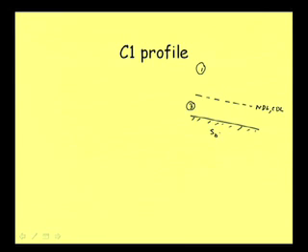So, here SB is equal to SC, and of course, it is positive. Well, so this profile C1 will be a rising profile like that, because we could see that if the flow depth y is more than yn, then we always get a rising profile, and suppose this is our depth y.